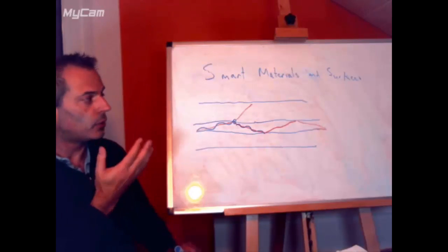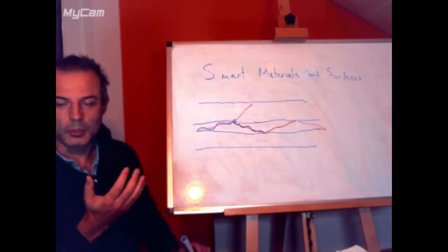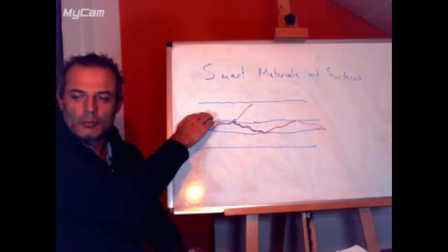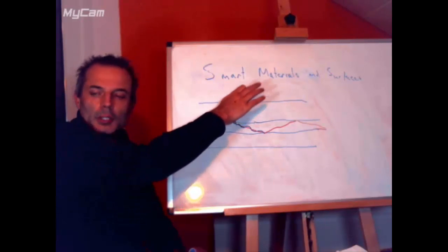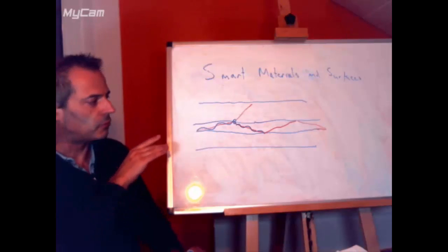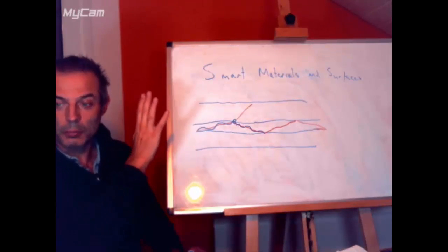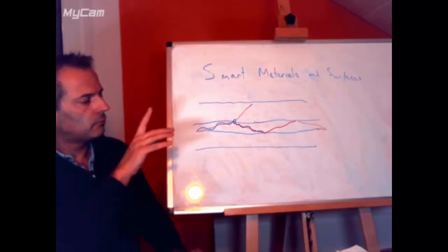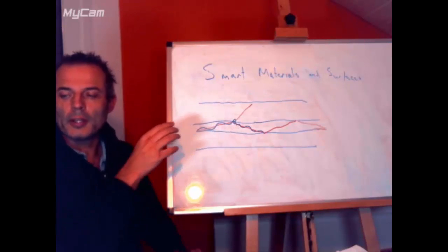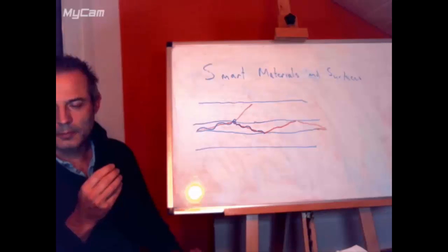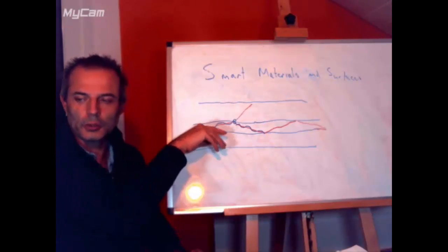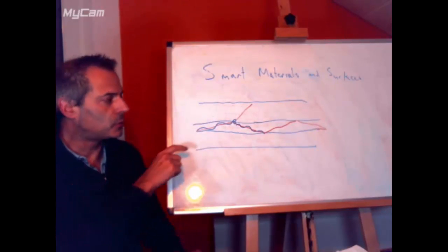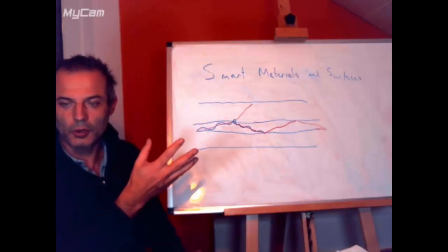If we do this with optical fibers, we can insert them into other materials and we can measure things. So what we can measure is the refractive index of outside, because that will determine how much escapes depending on wavelength. So if we send white light on there, we'll lose some. If we attach a molecule on there that could absorb one of the colors of the light, then some of the light will get lost. So the light that goes in will come out with missing some components which were absorbed here at this point where it bounced off.